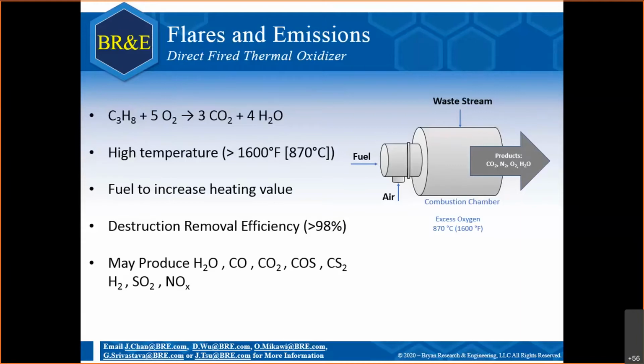However, if the combustion is not complete, such as if your oxygen is insufficient, then carbon monoxide and H2, your hydrogen, may form as well. So you may need to take note of that. If sulfur species are present in your feed, such as your H2S, then products such as your SOx may form. And similarly, if you have nitrogen species present in your feed, such as your ammonia, then NOx products will form.